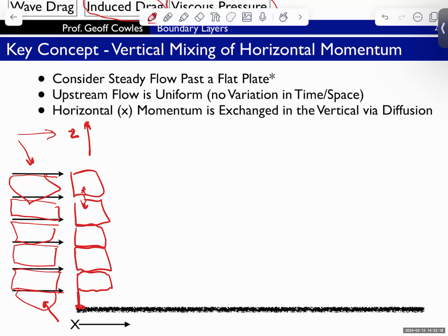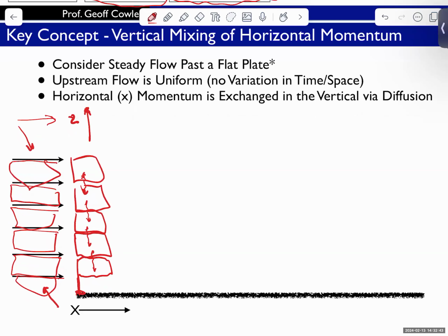This is also a diffusive process that we're talking about here, but it's diffusion of momentum. And so momentum is diffused among these parcels at relatively low rates in this laminar case. And we'll contrast this with the turbulence case on Thursday, where the diffusion is through a different mechanism, which are eddies in the flow. A much more rapid mixing of momentum occurs. In laminar boundary layers, this is a slow process, but it's always in play.